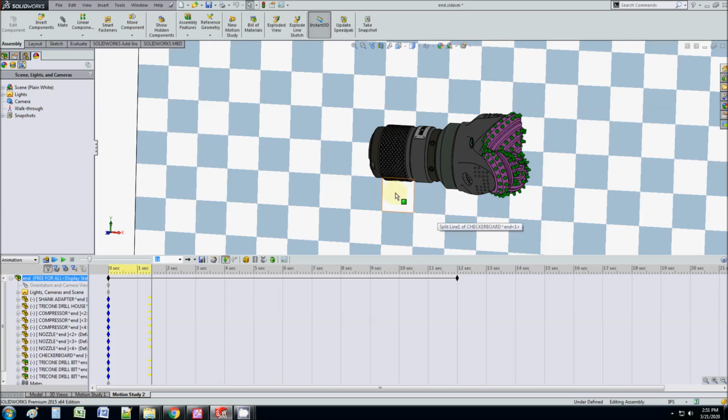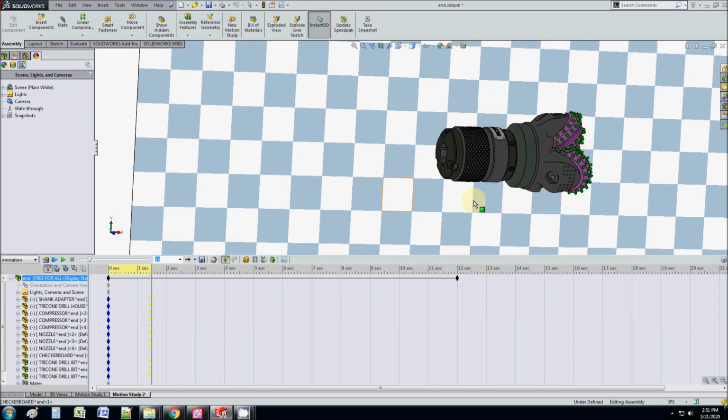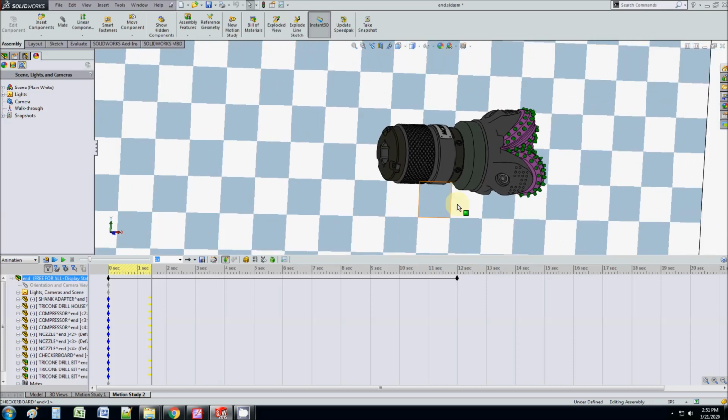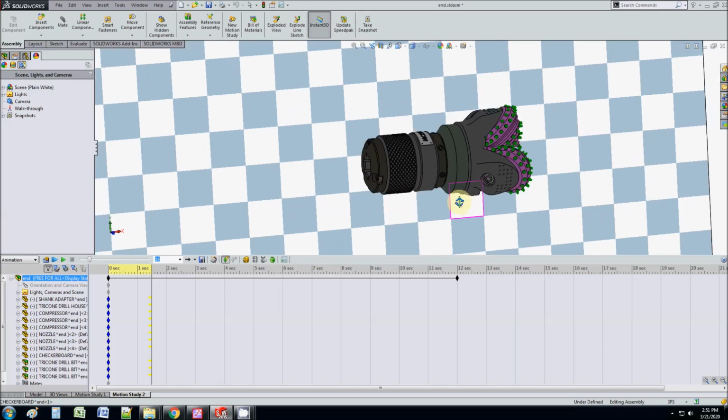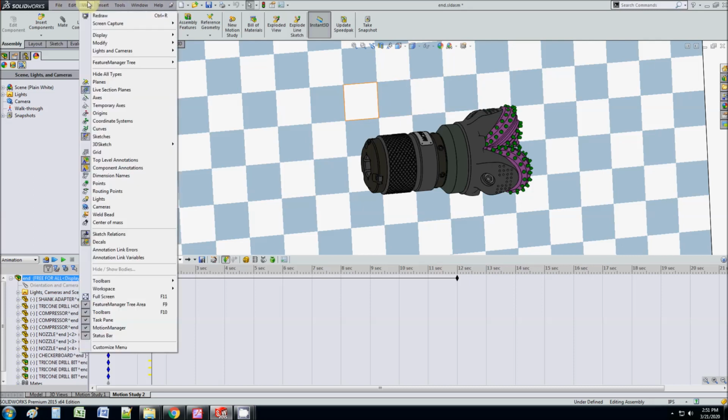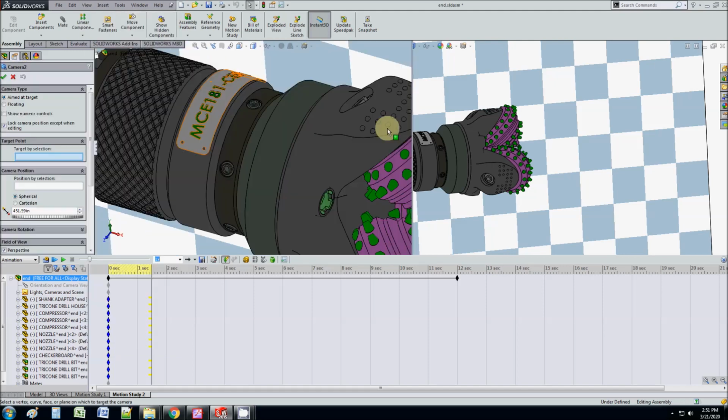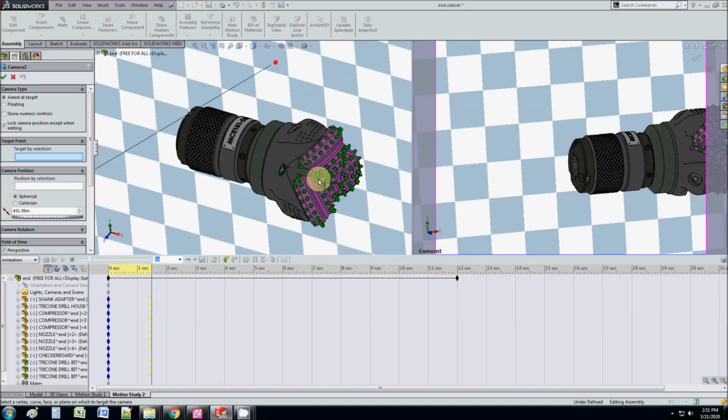Because right now when I'm recording, I'm really just recording from the viewport. And that's kind of inconsistent, because I could be recording from here once, then I could be recording from there. It's just hard to keep track of that. What I want is to be able to select a camera from here and have a really consistent view of what I've got. So I could have added this since the beginning, but to add a camera, you go to View, Lights, Cameras, and Add Camera. You can also add a light. A light will really get you exactly what you want.